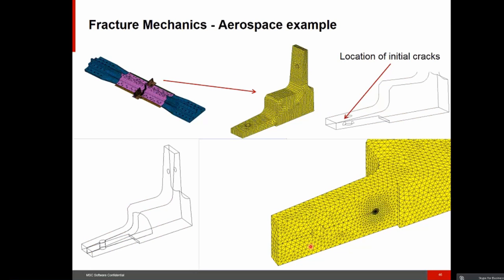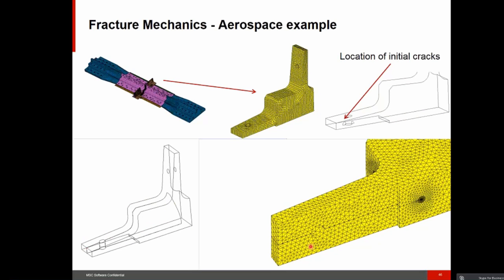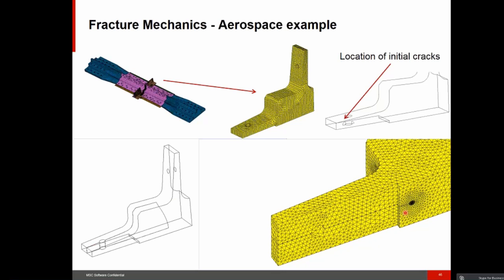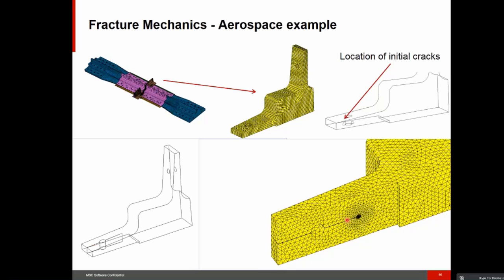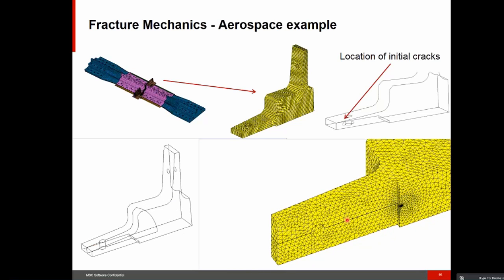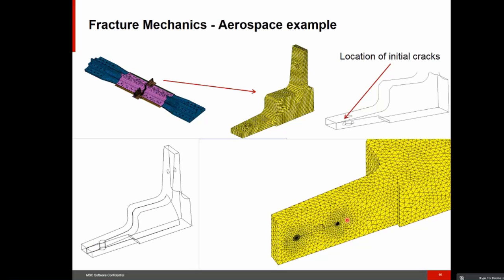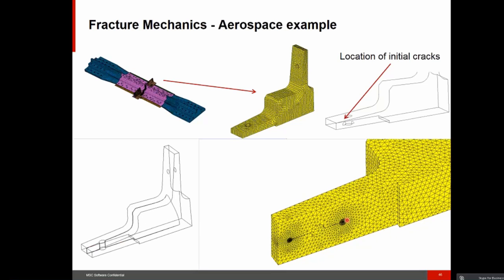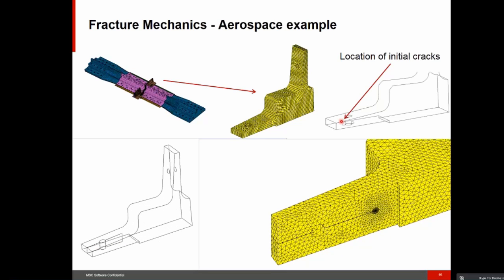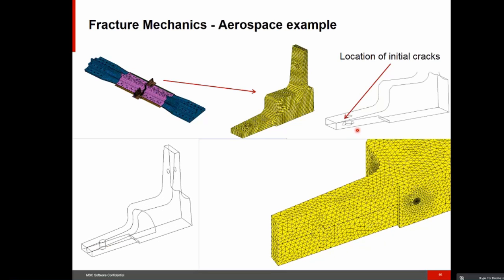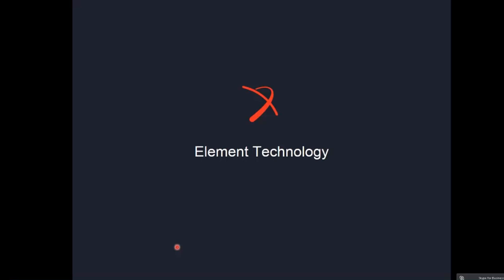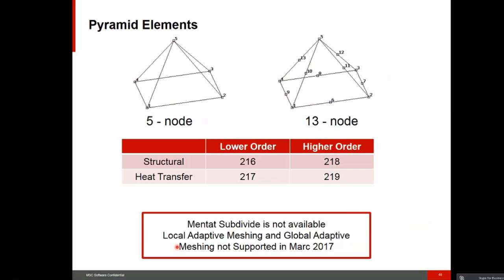This is being applied to complex problems such as this. And again, you see a very regular finite element mesh tracking the crack point, the critical crack area during the crack propagation, where initially we had initial cracks of this size, and we see the propagation.